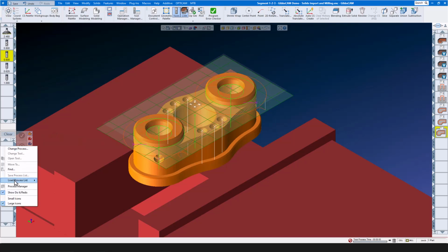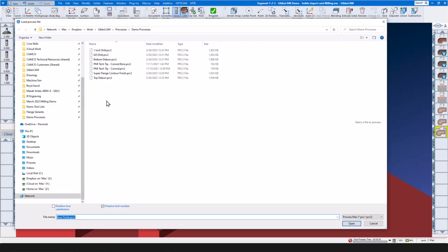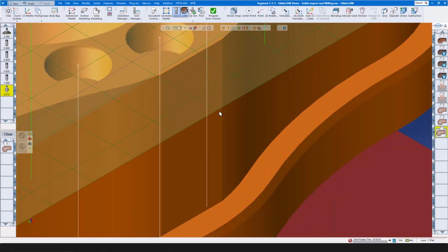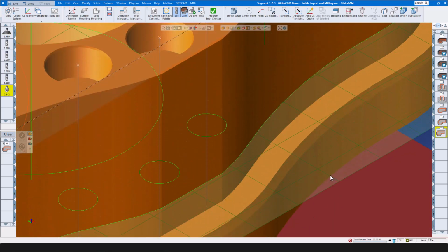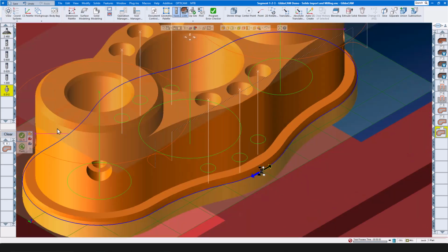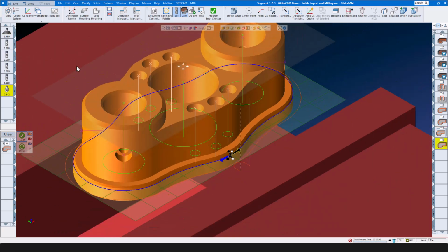The chamfering processes, along with the chamfering tool, are already in the demo process folder. Bottom deburr has the final depth for the bottom deburr. When we import it, up comes the tool, up comes the process with the right dimensions. All we have to do is drag the profiler down into the bottom of the part where it will highlight the geometry. We click on the geometry and create the first deburring process.